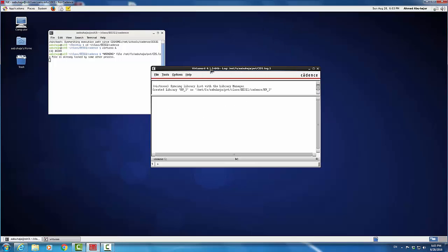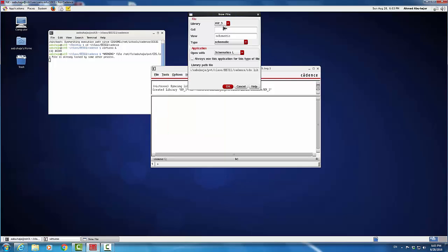So we already added it now, that's why we clicked on cancel. Now I'm gonna do a new cell view. That's basically the circuit, and then this circuit under the library homework 3, we're gonna say the circuit gonna be OpAmp circuit 1. So it's gonna be OpAmp circuit 1, and make sure that the application gonna be the ahdlLib tool.